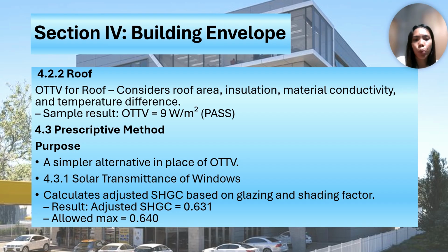Prescriptive method: the purpose is a simpler alternative in place of OTTV. So instead of computing OTTV, each component like windows, walls, and roofs must meet fixed limits.